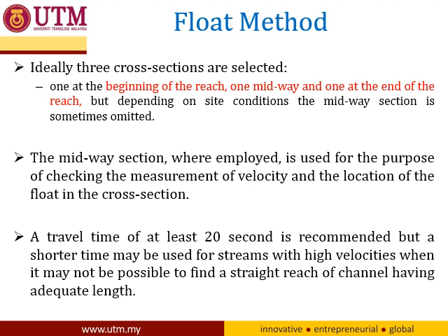Okay, this is just some more guideline. A travel time of at least 20 seconds is recommended, but a shorter time may be used for streams with high velocities, when it may not be possible to find a straight reach of channel having adequate length.